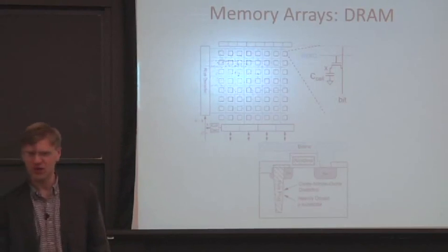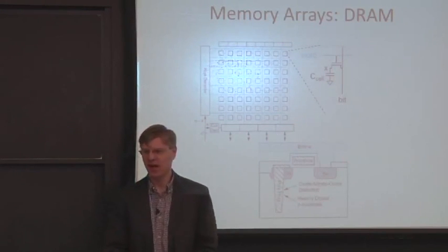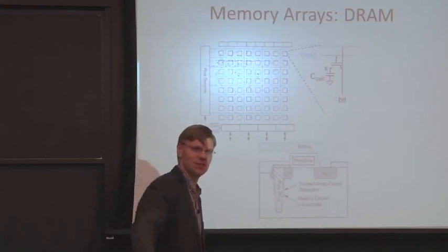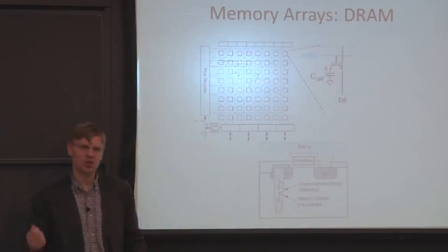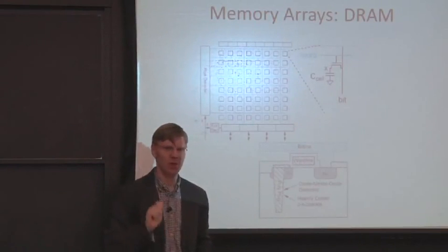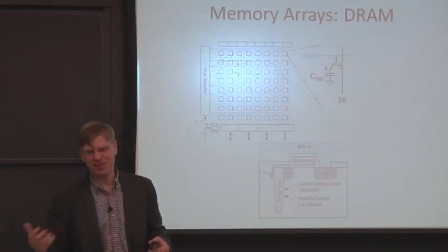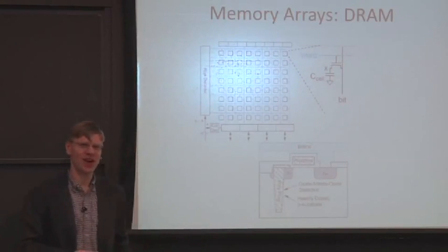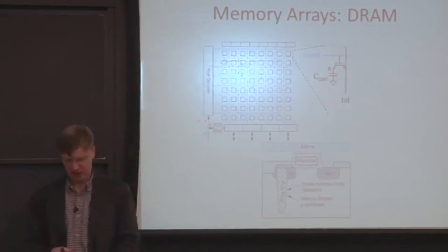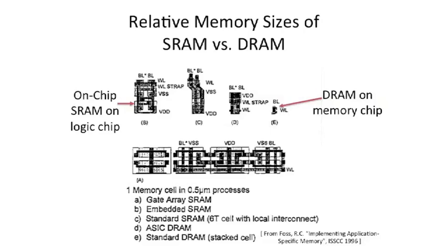Most RAM is actually decent now, and you've probably seen some attacks that people have built around this. There are some encryption attacks where people will effectively turn off a computer, pull the RAM out, and stick it in a different computer. The DRAM will still hold the charge, still hold the information, even after you remove the power from it, because this is a bunch of little capacitors that store that charge. That's a funny little case where DRAM ends up being a negative, but we're really doing this to have more space to store data, because each of these bit cells is a lot smaller.